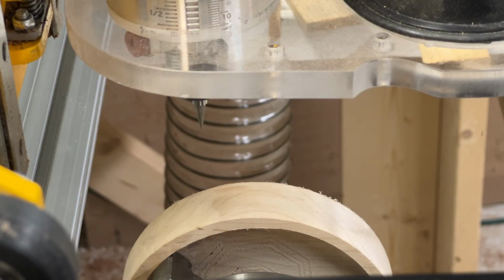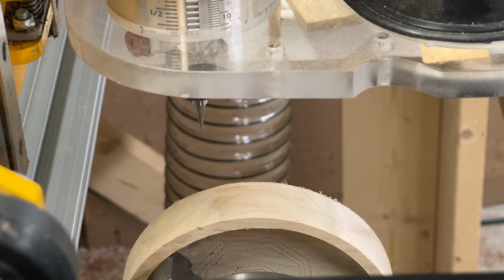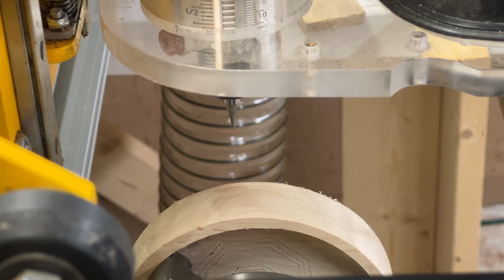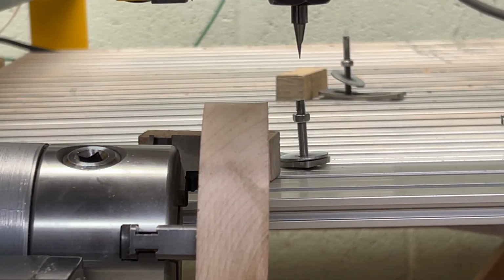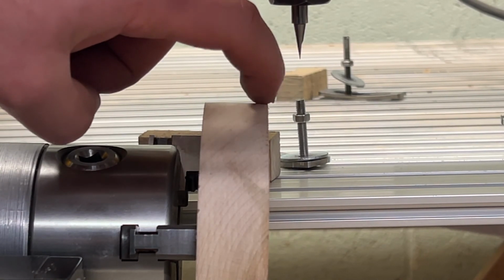Okay, so here we are trying to set the y-axis. So I'm going to jog the machine until it's in the center of the coaster here. 0. Now we'll set the 0 on UGS and move on to the X. One more time for the X. What we want is the tip of this cutter to be at the very leading edge of the coaster.